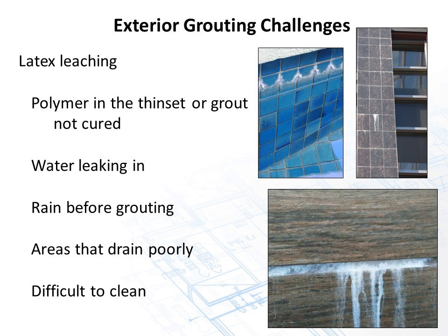Think about latex leaching like this. If I took a gallon of latex admixture, put it on my desk, took the top off it, the water would eventually evaporate away to where I'd have a little ball of latex at the bottom of it. If I kept the lid on it and the latex stayed in solution with the water, it'll always remain a latex liquid solution. If the latex in a mortar or grout is not allowed to dry, it can't become a solid, so it is water soluble. When water leaves that installation, it'll take the latex with it, allowing it to leach, if you will, to the exterior.